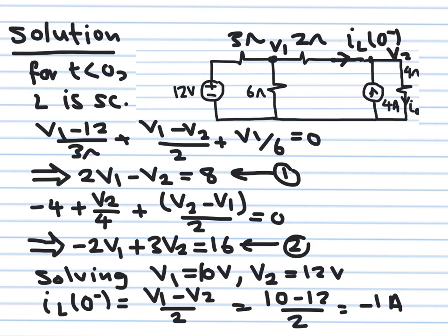Okay, so it's a circuit like any circuit we have solved before. I have here 1, 2, 3 loops. I have only 2 nodes. I prefer to use node analysis. I found it easier. Remember that even though you have a voltage source here, because it's connected to a resistor in series, I can apply KCL here. There shouldn't be any problem. So applying KCL here, we have how many currents flowing out? One current flowing out, a second current flowing out, the third current flowing out. The sum of all these flowing out currents is equal to 0.